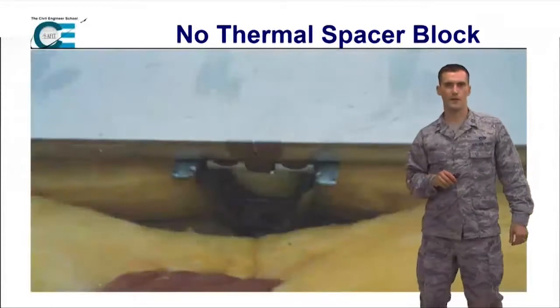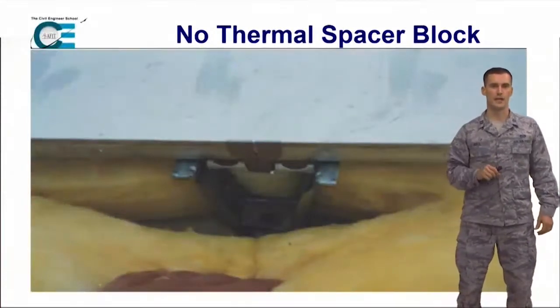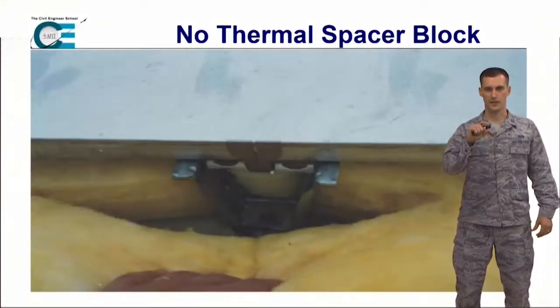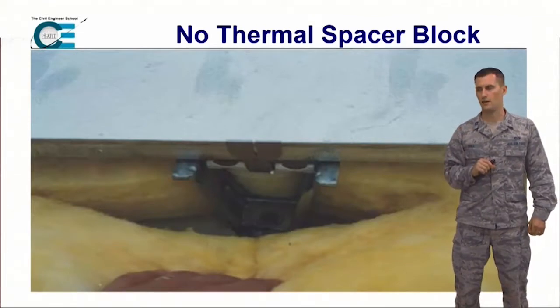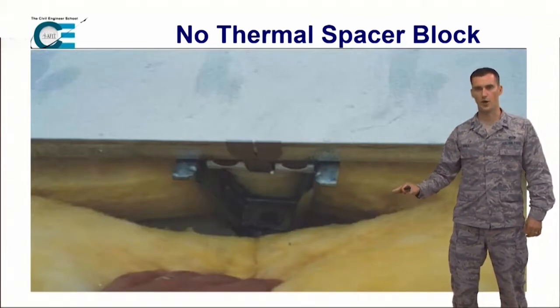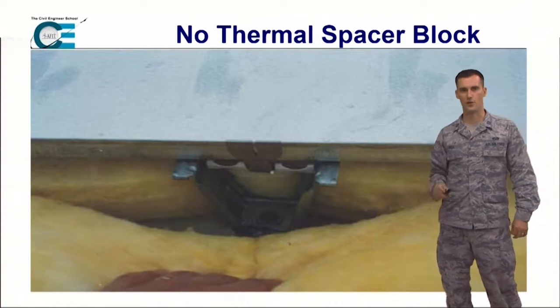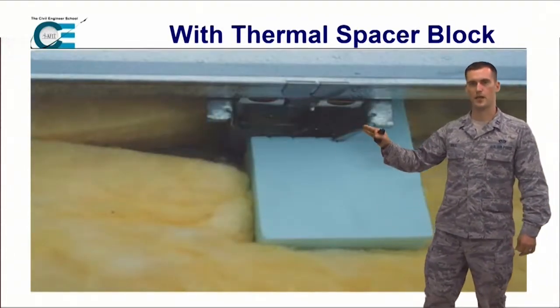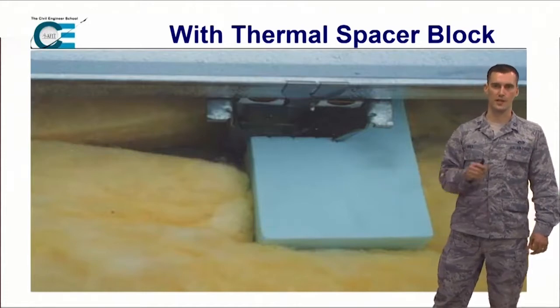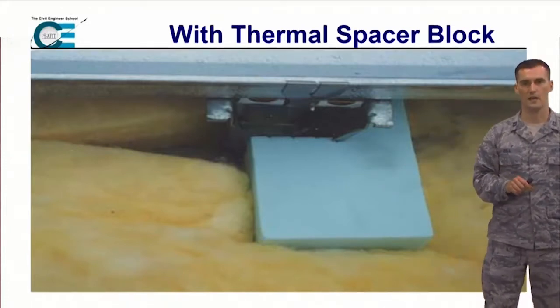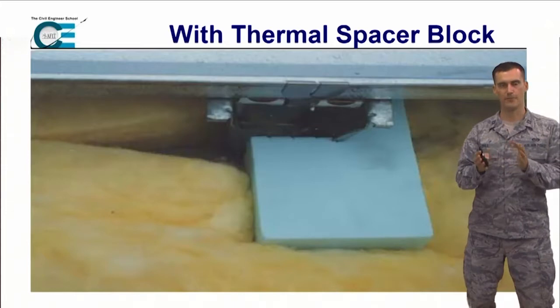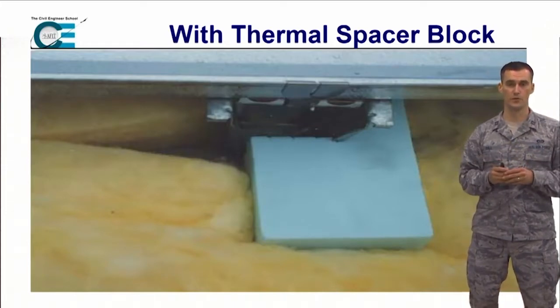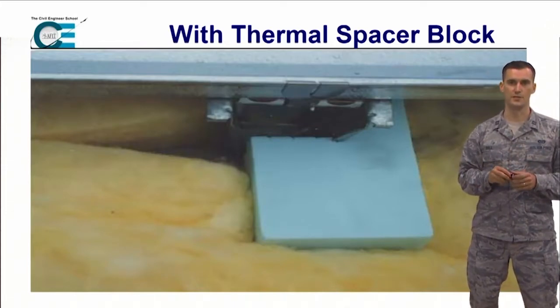Well, I apologize for the quality of that video, but hopefully you could see kind of what they were doing, installing what they call that thermal spacer along the purlins there. So, you're going to have a gap if you don't have that. And so what they're advocating and what they've come up with is that thermal spacer, which allows you to fasten that roof deck, but also provides some of the R value that we're ultimately looking for in order to reduce that total heat transfer.